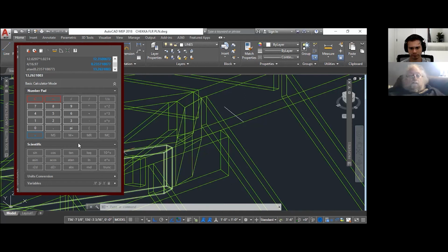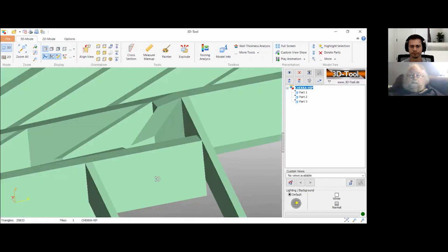Well, what's the cosine of that? And then 1 over x? Bingo. That's where I got my 1.0274. That's my secant of what this little hip is. In fact, it's the same secant for any length 4 and 12 hip. We're talking about the same thing right here, okay?